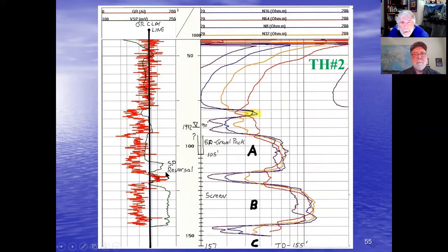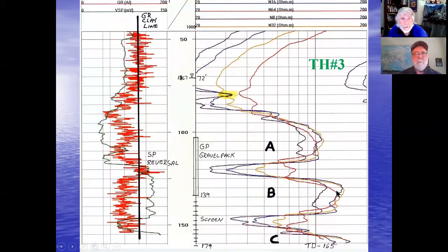And then as we move up right here around 110, 115, we've gone a little bit fresher water into less saline, and then it flips. So this unit is now saltier than the mud filtrate, and the same with this horizon. So qualitatively, we can look at this well right away and see which ones are better water zones. We ended up finding we had to isolate this zone from these other zones to get the client cleaner water.